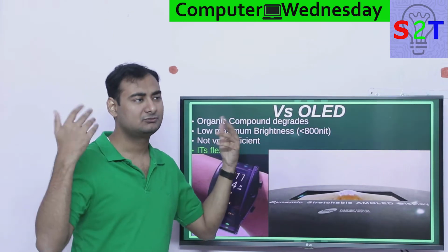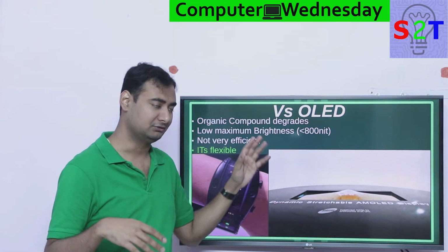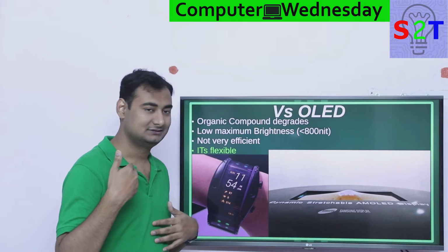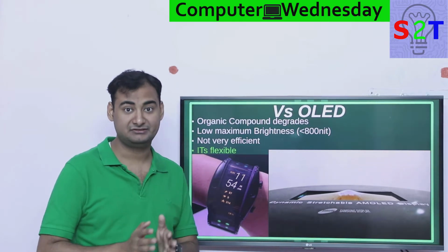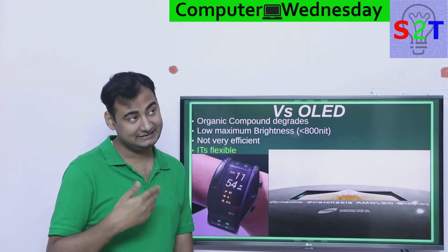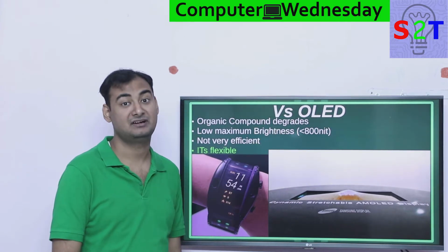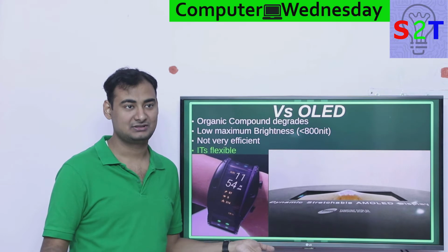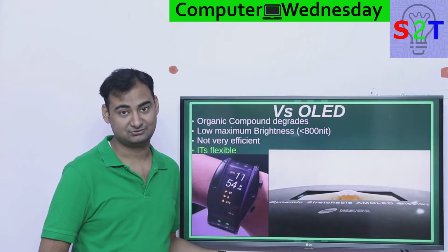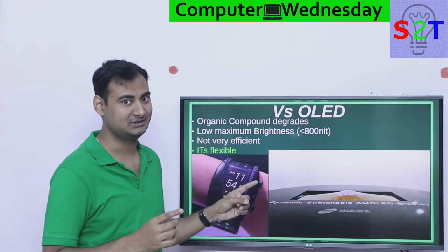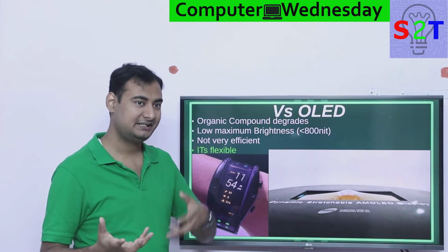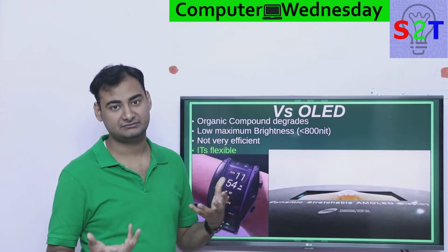It's not a, oh, it would be better to have it; it's an issue. On top of that, because of the HDR specification, the maximum brightness you need for full HDR is 1000 nits. So can AMOLED push that? Yes, they can push it, but they will degrade much faster. So LG would be in a position where I can make an OLED that is awesome, but it will last only 1 or 2 years. And if you are spending that kind of money, people are like, dude, I want this thing to last. So it's not that bright, and not only that, it does not last very long.